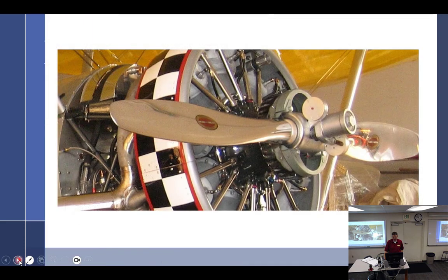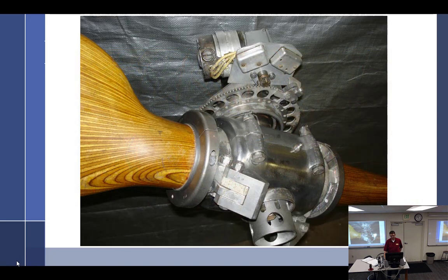All right, then we have a constant speed 2-position Hamilton Standard propeller. This is only a 2-position prop. The 30. High gear, low gear. No in-betweens. It's gorgeous, huh? By the way, see how the prop is all polished? Yep. I believe that Hamilton Standard is the only propeller that can be polished. Any other propeller that's polished, there was a few years back where the FAA was really cracking down on that because it violates the repair manual for the props, because they all end with "and paint."